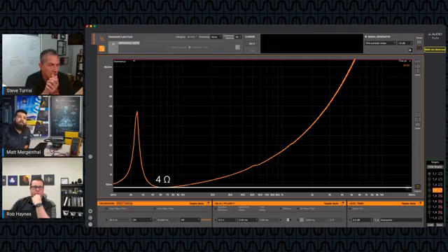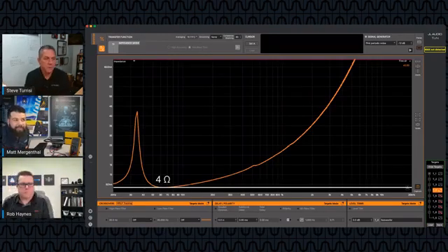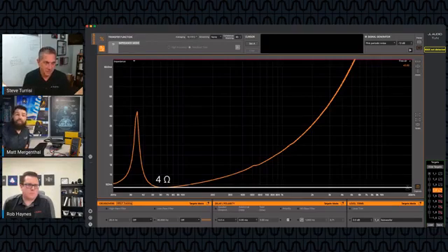This is considered a 4 ohm speaker, which we just measured with our multimeter. Actually, again, this was the subwoofer, but the only place where it's actually 4 ohm is right there at the bottom where that line goes across the graph. Everywhere else, it's above 4 ohm. And I find it very interesting that at different frequencies, it's not 4 ohm. Mainly it's between 55 hertz and maybe 85 hertz that it's actually 4 ohm. I would contend that it's rarely 4 ohms.